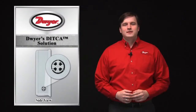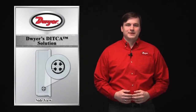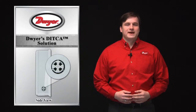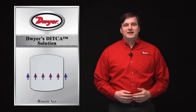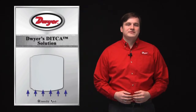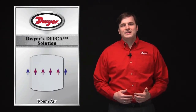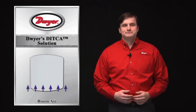Featuring the Dwyer patented Digital Intelligent Temperature Compensation algorithm, our combination sensors eliminate errors in the RH readings caused by the natural internal heating effects of wall mount combination sensors. The circuitry needed to drive NDIR sensors creates heat inside the enclosure. Since wall mount sensors are not typically mounted in a location where there is significant airflow to draw this heat away, the result is typically a higher temperature reading and lower RH reading than the actual conditions in the room.